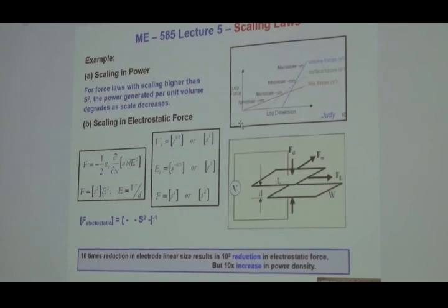They have energy storage, but batteries are energy storage. But why are capacitors sometimes better than batteries? Well, it's quick release. They're releasing energy in a quick, fast release, which is power density. So, for example, if you're operating a big bus, you want to accelerate a huge mass. In fact, they have big markets in buses, because buses often stop, brake, and then start. If you want to start with your electric motor, there's no way you're going to accelerate fast, because the battery is going to deliver very, very slowly. With capacitors, they can do things very fast.